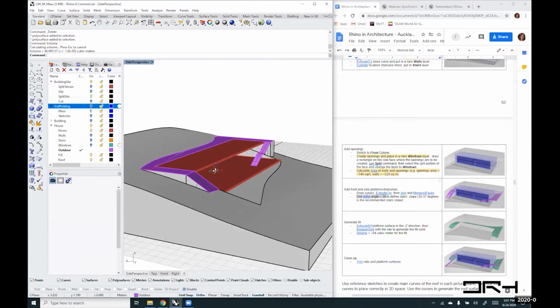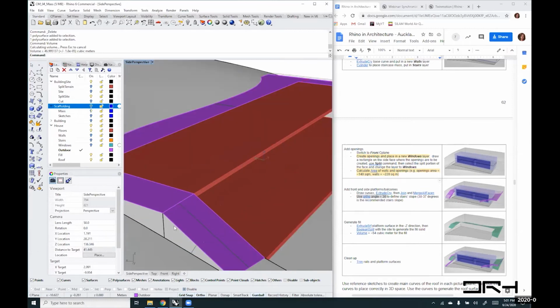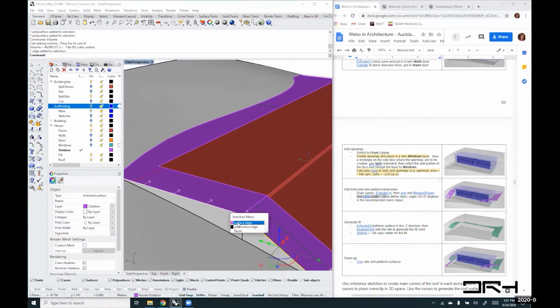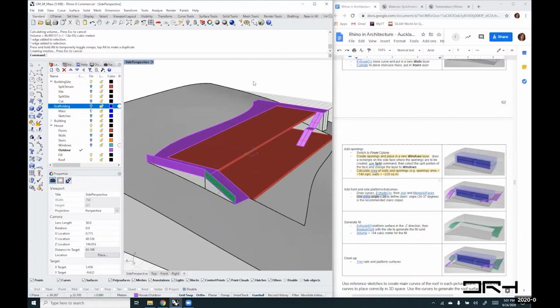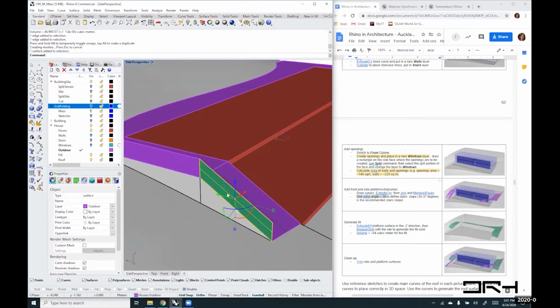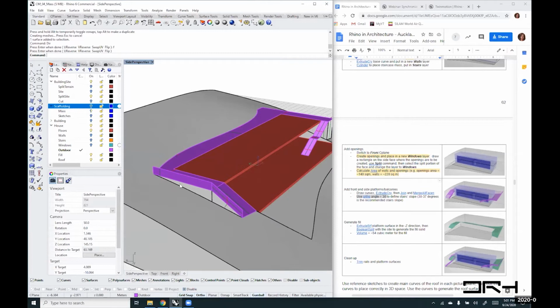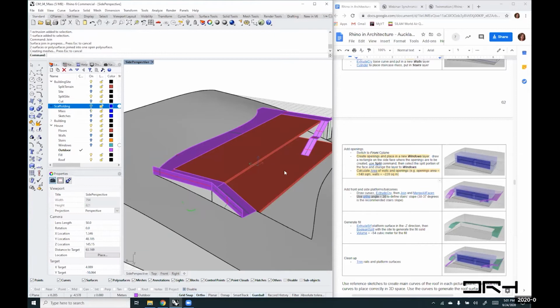All right. So that's how we create that fill, and we do have these platforms that we can also just create a rough railing out of by sub-object selecting the edges here and extruding it up a little bit by, say, 0.8. And this way you can see some sort of a beginning of a railing. I'm just going to change the direction to make it consistent here. And I can join them together. Of course, you can add any amount of detail at that point.